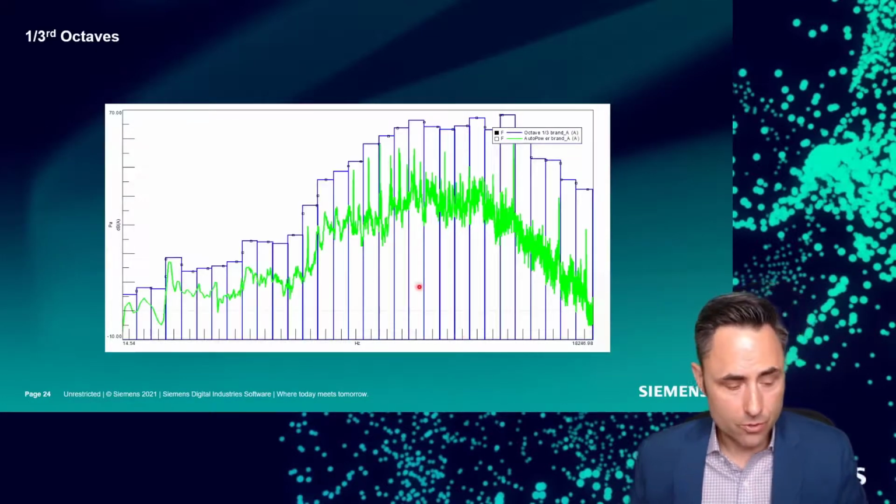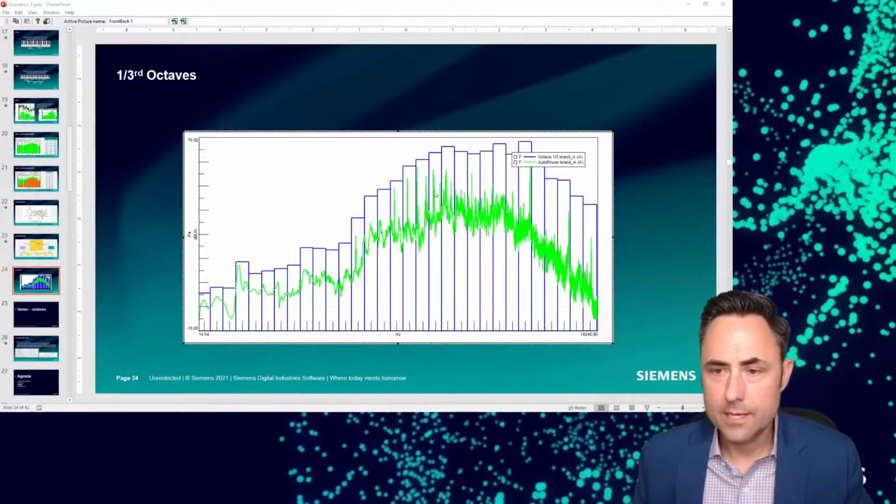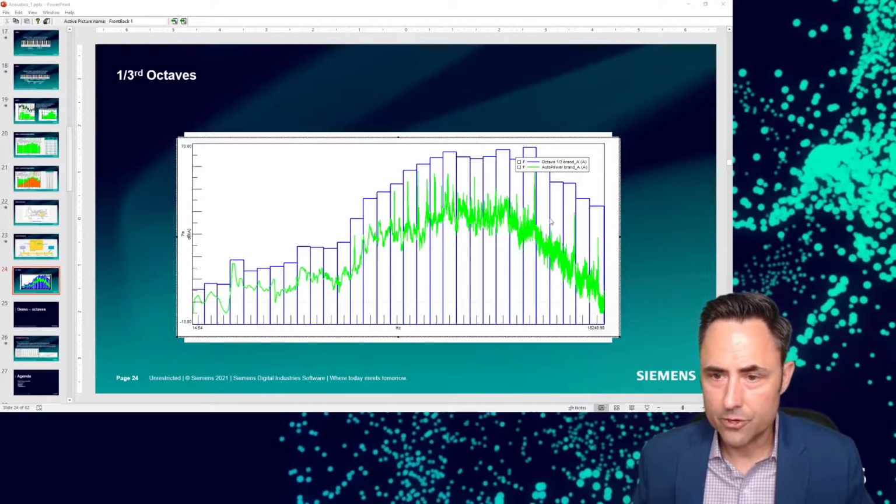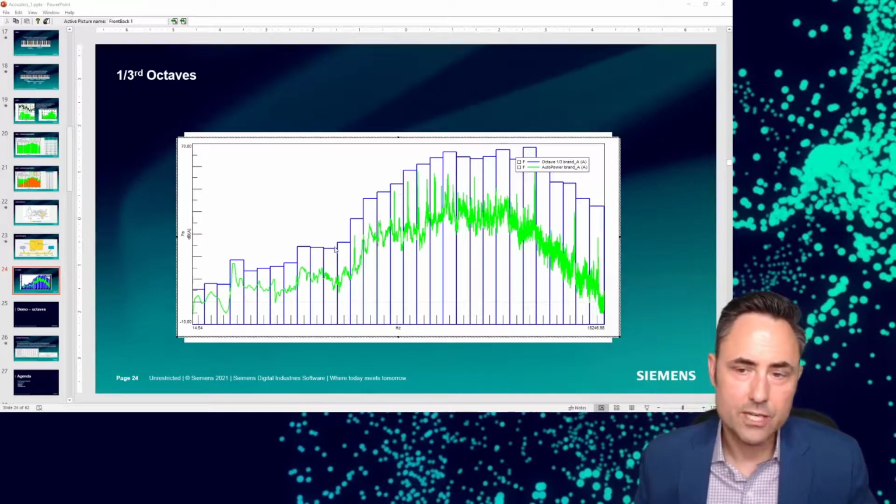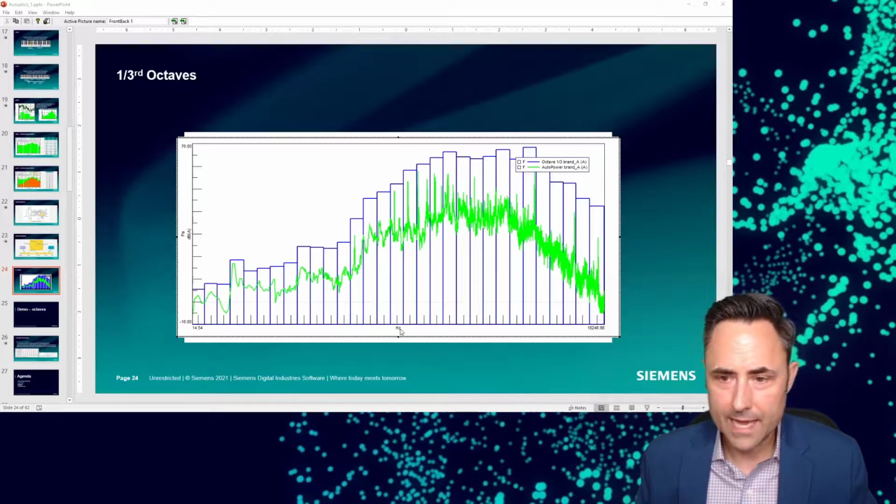Okay, and so the octave band here is really just another way of looking at our narrow band. So I'll activate this picture here. If we look at that narrow band frequency, I see I have the 1/3 octave band frequency, but you see how spread out the narrow band data is behind it and how smashed together it is out here. The blue and the green are the same information. It's really just whether I'm plotting on a logarithmic axis or a linear axis.